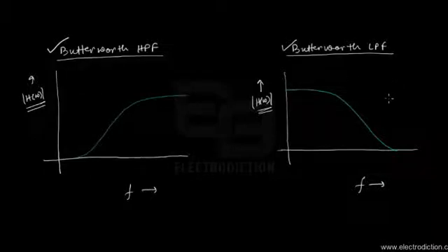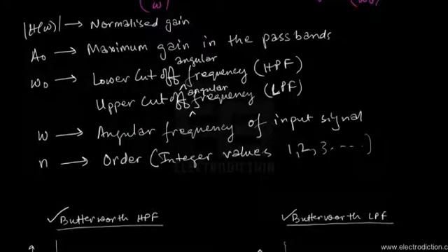for the high pass filter, we can see that as we go on increasing the frequencies, the gain increases with a gentle slope, and then starts decreasing at a particular value, and moves on to have a constant or a maximum value after a certain frequency. If we produce a line from over here, this should give us the maximum gain experienced by the high pass filter. So this is going to be A0. A0 represents the maximum gain for each of the filter's passbands.